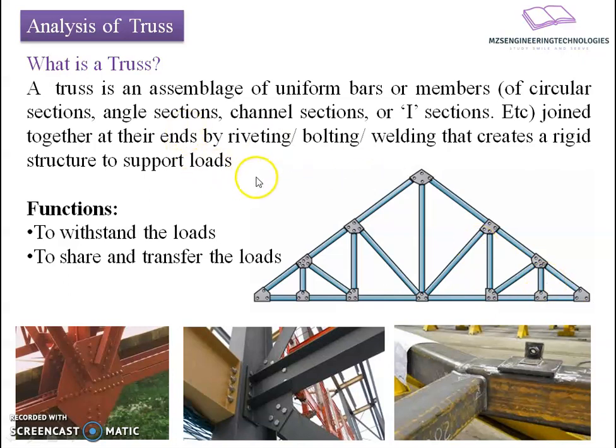The connections are made with the help of elements which create partial rigidity or rigidity in the structure. For example, if we move from the right hand side, we see here there is a welded connection. This connection is said to be a rigid connection where there is a complete seizing of the end, and this connection is made with such a metal that it possesses the same character as that of the parent element. Thereby, it acts as a very rigid and secure support.